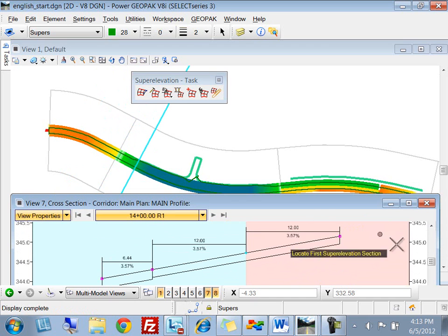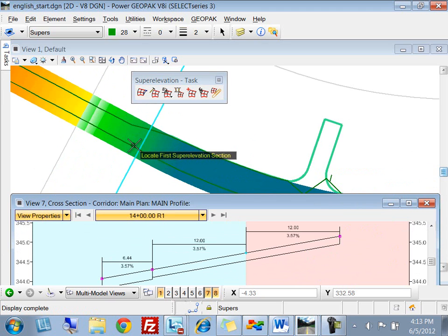And now you'll notice in this one we have the beginnings of a turn lane. And if we move in a little bit, you can see the turn lane is starting here. But you'll notice that my super elevation lane actually goes outside of the turn lane. And that's fine. It's going to build the turn lane based on either my template, or in this case, on my turn lane graphics. And so it knows to draw my supers based on my super lanes, but it will stop at the edge of my graphic. And so it basically ignores any of the super elevation lane that's outside of that. And the same thing is happening down in the area where there's only one lane. That second super lane that I drew in is being ignored as well.